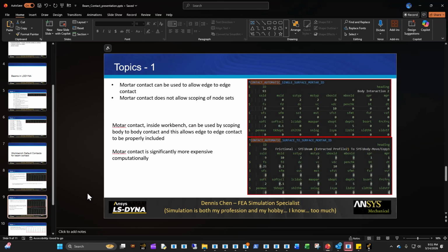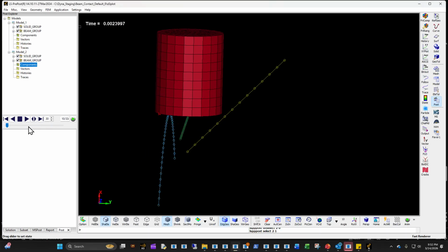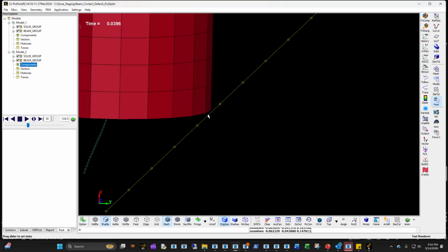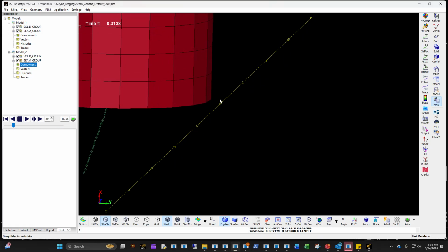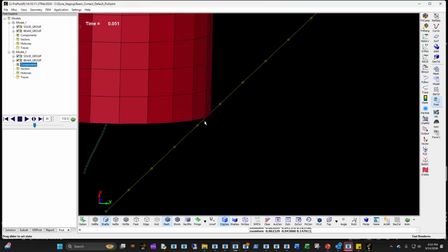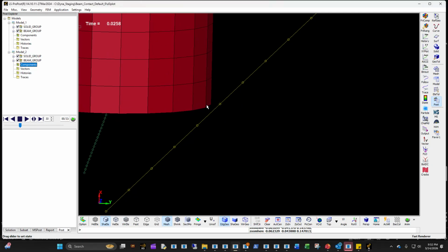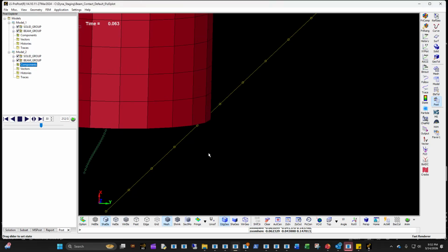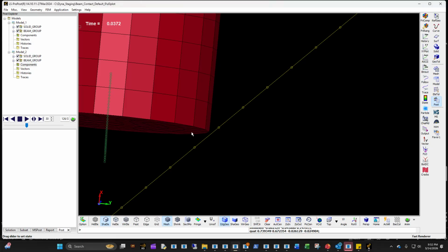What we can also do is to have a much better detection. Say for example, if we only do automatic surface contact, what happens is that you have this initial penetration right there that happens between the automatic nodes to surface contact. That doesn't actually do a very good job, right? You can see it doesn't really detect that end of it until you get to the segment, until you have some penetration that eventually gets resolved, because the contact starts later in that contact pair.